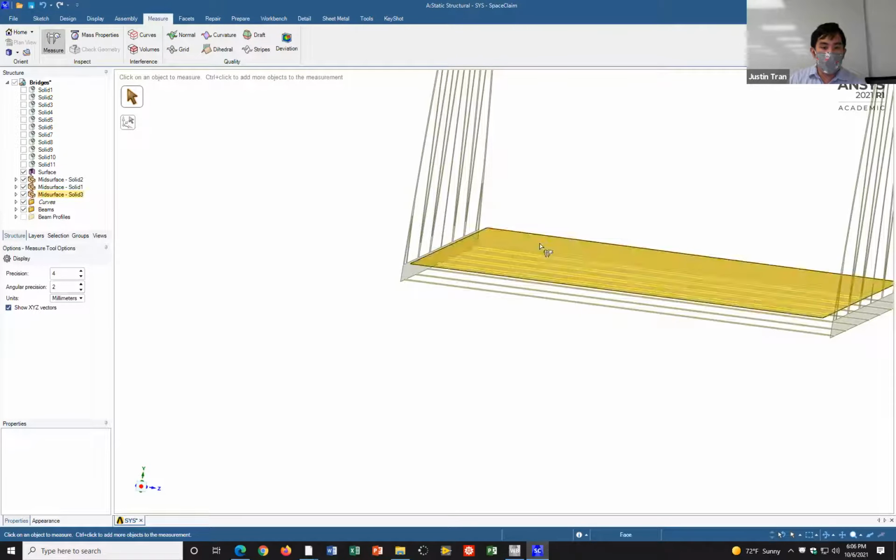From here, we have to do a few things before we start to mesh and apply boundary conditions. The main thing is that because we've converted everything to shells and beams, Ansys has no idea which parts should be connected to each other, so we need to manually add all the connections into this geometry to tell Ansys which parts should be bonded. We're going to be spending time under this connections tab, creating manual connections that connect the different parts of this assembly.